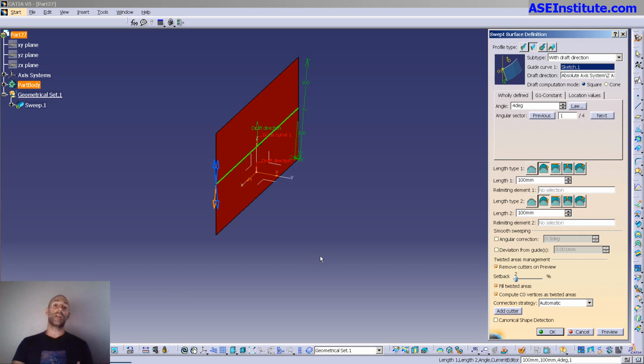So for those people that have an aversion to fill, just use fill. It builds the most stable, sound element. It's easy, you know what it is. It's not going to fail unless the sketch itself becomes an open element. The normal isn't going to reverse. You can switch it from one plane to the next to the next. It doesn't matter the direction. I'm talking about the sketch that makes the fill, and it's always going to stay the same. The surface itself isn't based off of the plane. It's based off of the sketch.